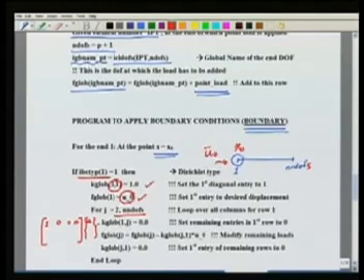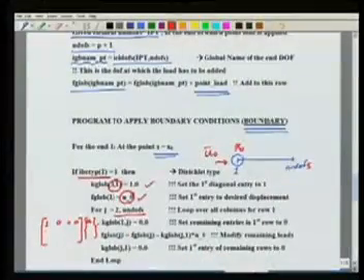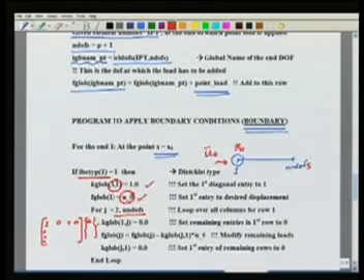Okay. Now what do I have to do? Since in the remaining equations also u0 is sitting there, I have set this 0, I would like to now keep my stiffness matrix symmetric. I could have left it as such, but by leaving these entries here, these stiffness entries which are not equal to 0, I am destroying the symmetry of the stiffness matrix. So now to make the stiffness matrix symmetric, I simply eliminate this known degree of freedom from the remaining equations.